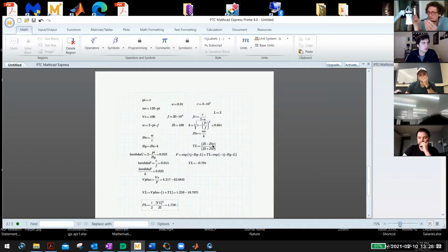Now, when you're getting into things that are 1/3 or half or 2.5 wavelengths long, then that looks like an actual transmission line. For a waveguide, this is important. The wavelength in the guide, not free space, has to be at least 1/10 of the wavelength in the guide, which is different than the free space wavelength.